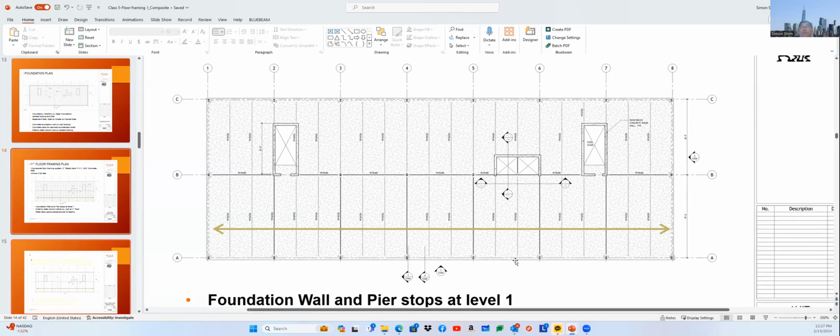Concrete core wall, you see that too, concrete core wall. I think I meant this to be stair shaft wall and elevator shaft wall here, right? They work like a vertical wall support, supporting the beam, to support the slab. So the beam is framing into the wall, right? So the wall is going to support your gravity load. And girder is obviously a beam. And if we don't have any wall, obviously those areas should be supported by the column and the girder, which are tying the columns.